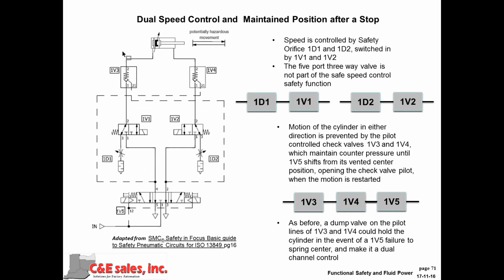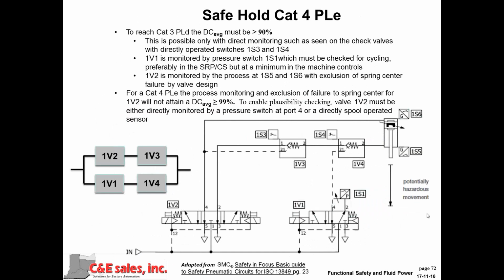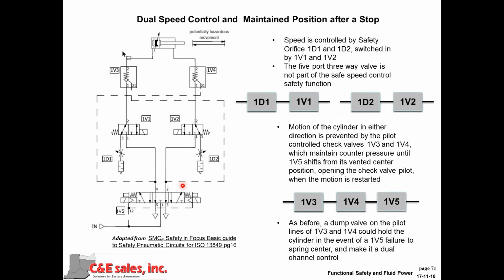This is an example where we use a 2-way valve and a safety rated speed control, so that perhaps in the manual mode, we bypass the interlock gate, which normally would shut off the hydraulics down here, or, in this case, air, this is an air drawing, would close this off to provide the safety. But since I have to move that cylinder in my setup mode, I provide a slow speed so that I increase my ability to escape, reduce my risk in that manner.